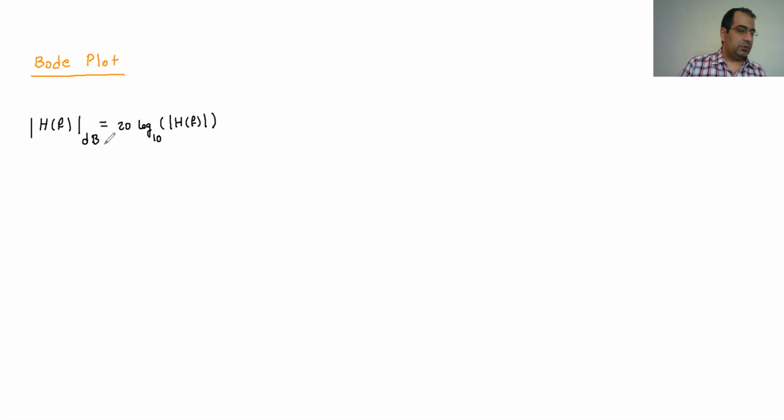I'm going to show you how it happens. First I'm going to draw it for the low pass filter, and then for the high pass filter, the first order low pass filter and first order high pass filter, to see how they look. The most benefit it has is that it's much easier to follow what's happening than when you plot it in normal scale. Remember that when you're working with filters in the frequency domain, it's very common to plot everything in logarithmic scales. It usually makes it much easier to work with.